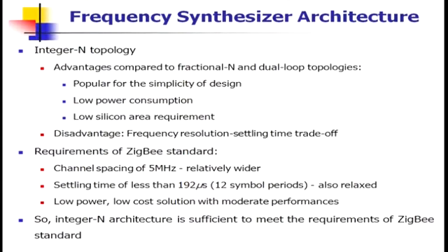So that 1 by n, say 10 or 5. Suppose 480, then next is 481 in the case of an integer mode frequency synthesizer. In the case of fractional, it will be 480.1, 480.2, and that way you will go to 481, then 481.1, like that. So you will get the fractional frequencies that will cater to the need of these 200-plus channels of a TV tuner, of any frequency synthesizer within the range of 400 to 670 megahertz. So that is known as the fractional-N frequency synthesizer.